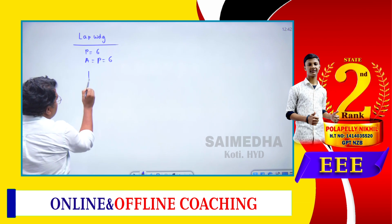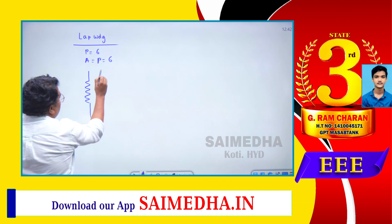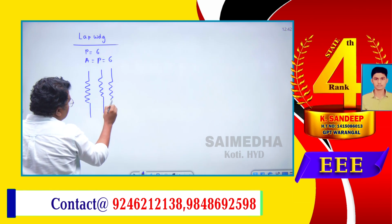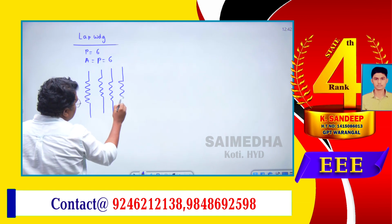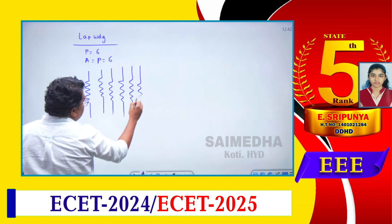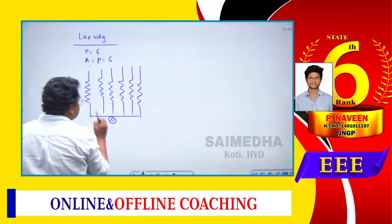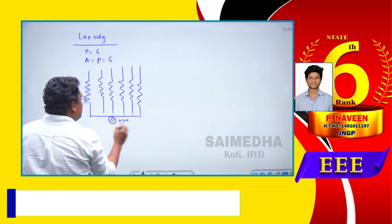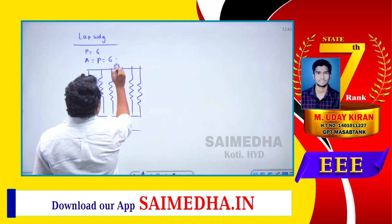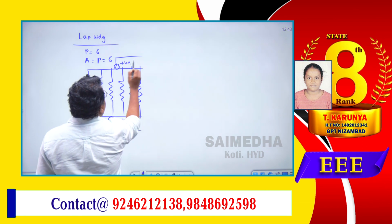Now let us draw the 6 parallel paths. This is the resistance per path, and similarly this is also the resistance per path, for all 6 parallel paths. These are the positive group of brushes, and these are the negative group of brushes.